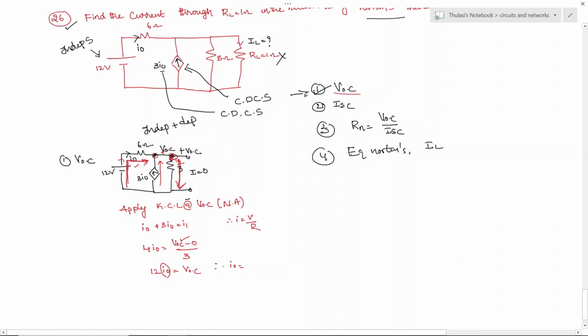Okay, so current is leaving. What is the leaving terminal of the voltage? 12 volts, and it reaches this point. Whenever it reaches this point, how do we write down I naught? So 12, this is a positive VOC, and this is minus. This is plus 12, and the leaving terminal of voltage is (12 minus VOC) divided by 6 ohm. So substitute this in this problem.